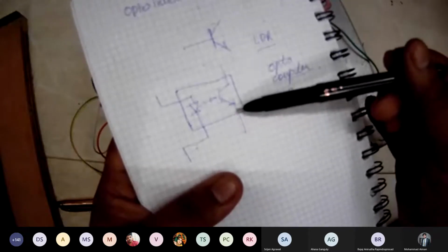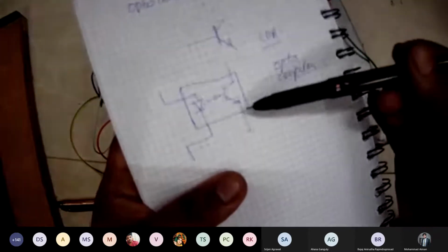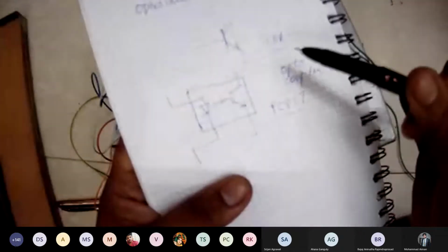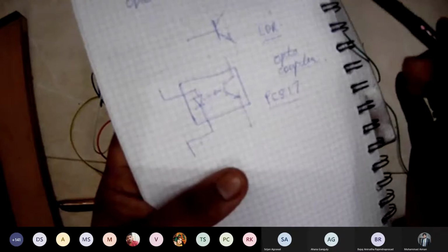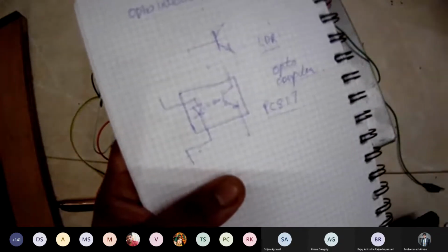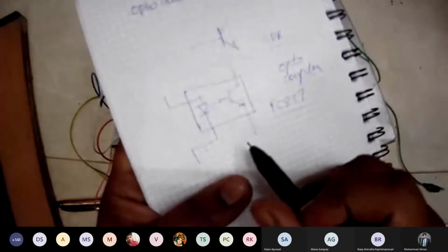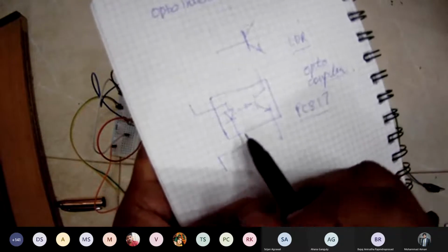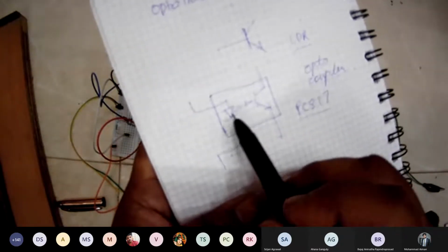While in a relay, you know that because of the sudden switching, it will also feed back and you can possibly damage the transistor. We've seen this in the last class. All right, so in order to complete this circuit, what you would need is to drive this LED.